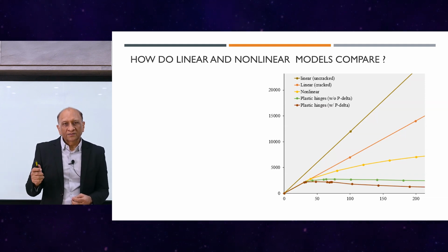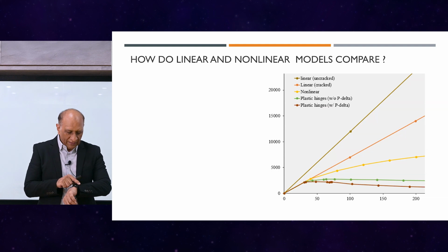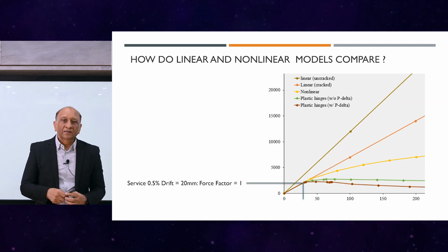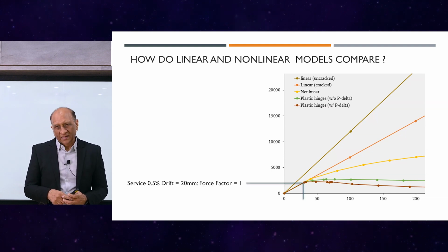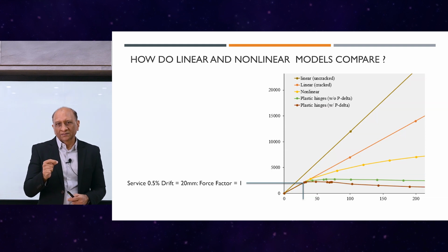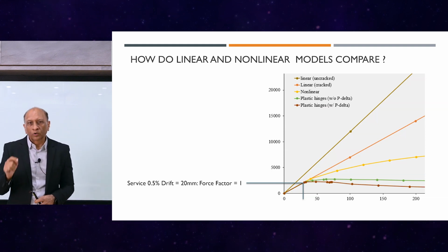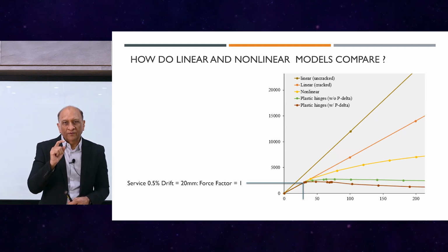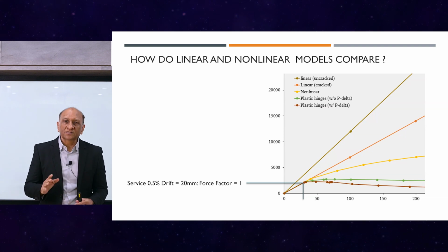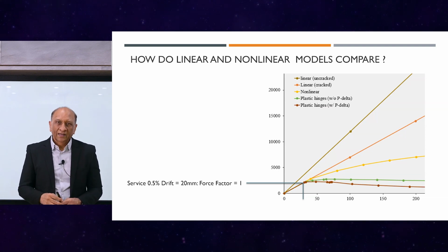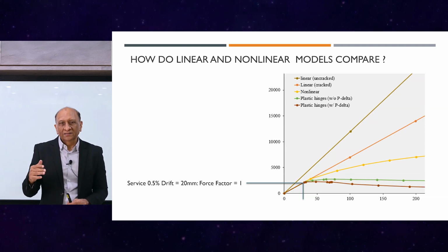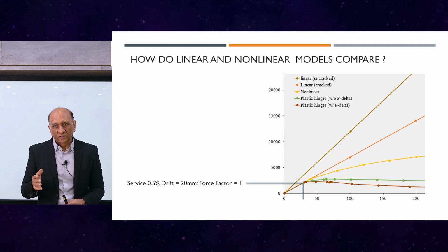Let me talk about the last part of the presentation. It is the higher modes and R. R, in general, has been derived based on most of the studies on frames which have a first predominant period. But tall buildings, on the other hand, have higher modes which contribute significantly.